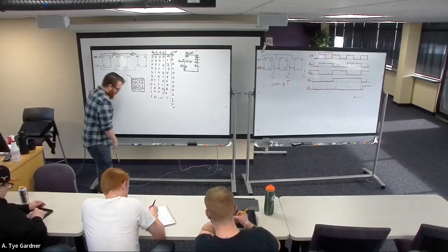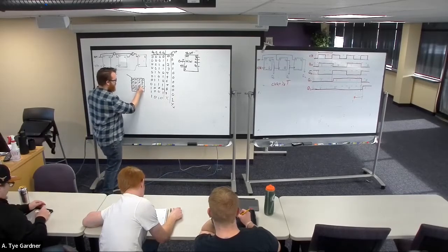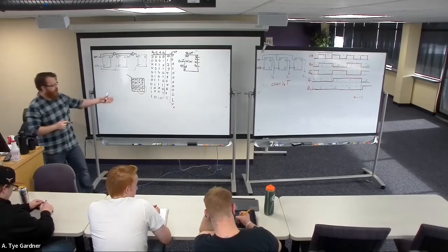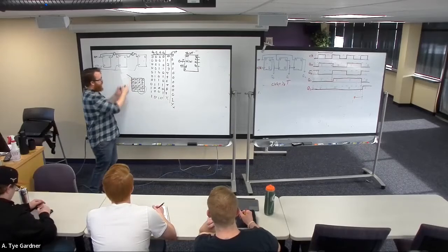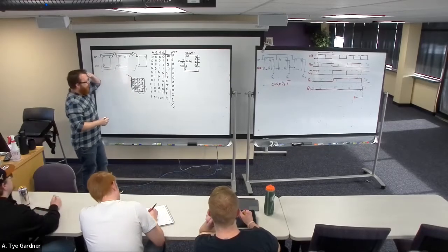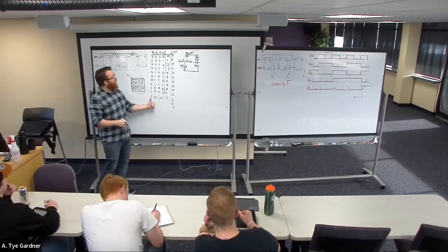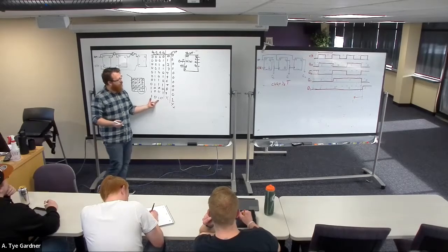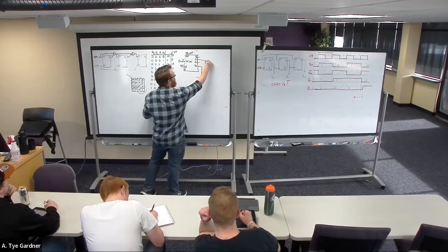That means I go ahead and circle my K-map. I only have 1, 1. That completes coverage. It is also minimized. I would need to figure out which Q's are where, or because we're starting to get good at this, I just look at it and go, the first time that Q3 is 1 and Q1 is 1, that's where I want to reset. So let's take Q3 and Q1.